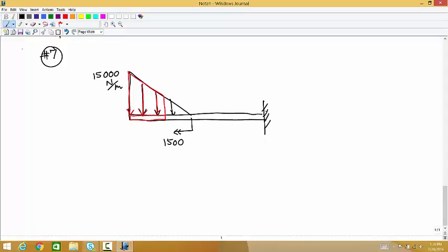We don't have to do the thing at the right, because we'll never get to that for the internal loads. So there are two places. No, that's not right. N is equal to 3. The two endpoints, and then the distributed load changes at the middle, and that's the same place that we have a point torque. So N equals 3. We're going to have to do 2 cuts. And the first cut is the unpleasant one. The first cut is the deepest. Cut 1 is for x values between 0 and 0.45.